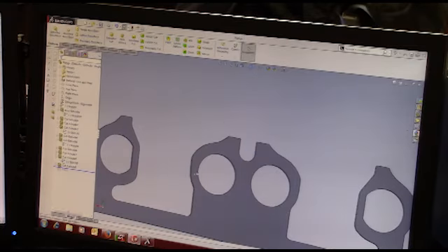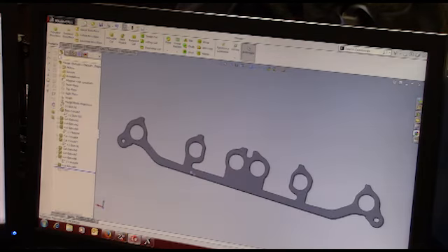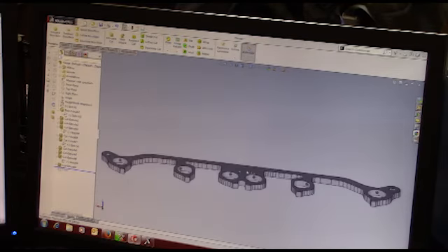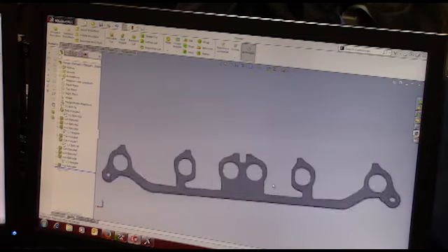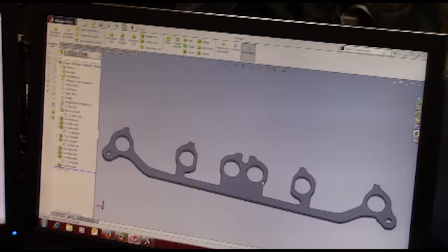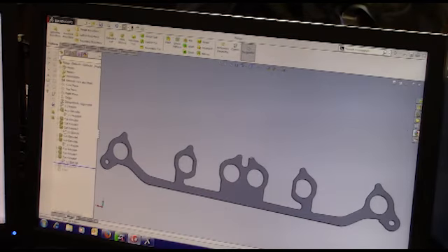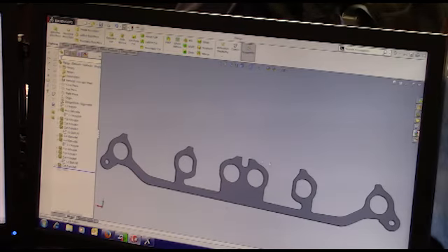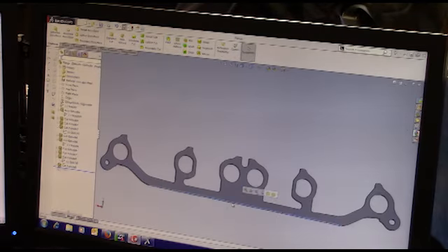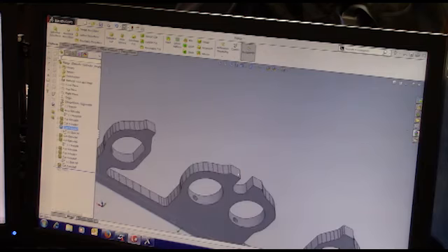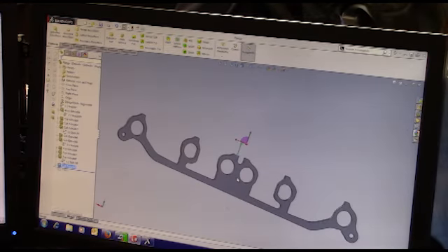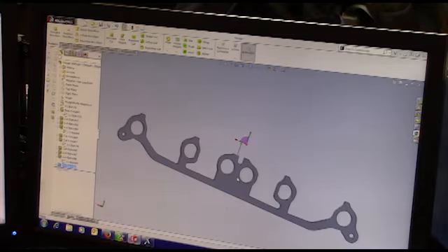And then the last thing we did was, once we have this part machined out and have the profile machined out, we have to flip it over and cut the material off the back side. So in order to do that, we're going to have to hold it in a vise or some type of fixture. So I'll go back here real quick, these are the normal tips that were on the top of the manifold. I ended up putting a cut in there that cut all those tips off. Again, it doesn't affect the function of what the client needs, but what that allows me to do is have two flat surfaces, this one here and this one here now, that are parallel to each other, machined in one operation, that I can now flip this over and hold it in a vise with.